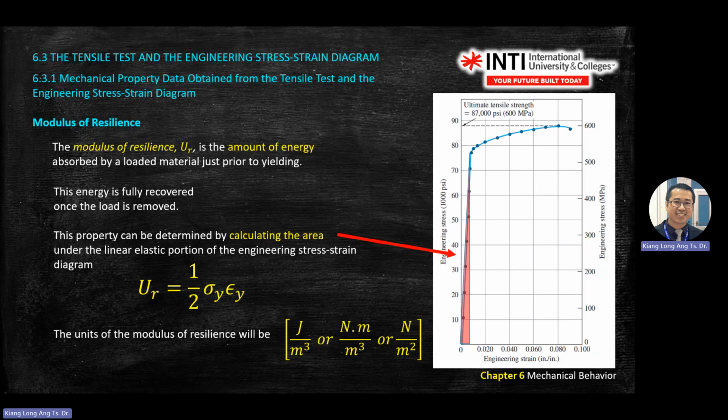Poisson ratio equals what divided by what? Longitudinal or lateral? Which one? Can you refer to your notes? What is a Poisson ratio? Poisson ratio is lateral divided by longitudinal. This is a negative value if it is a tensile loading. If it is compressive, then this one becomes positive.